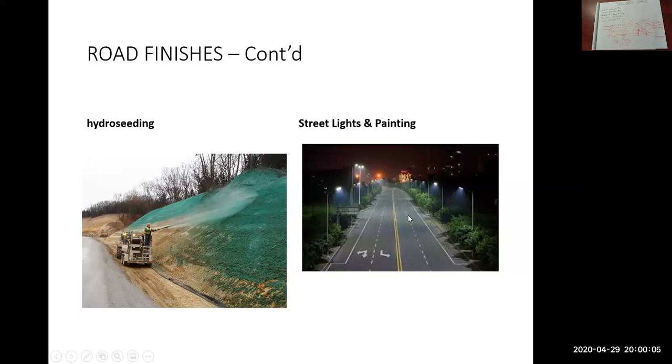The photo on the right here, we have some street lights. There's all the street lights. We've got paint, so you have fog lines or shoulder line here. You've got a dash line, double solid yellows in the middle, another dash, another fog line. You've got arrows that need to be painted. All that stuff will be shown on your drawings, so you can do your takeoff. Trees down the boulevards. Looks like maybe there's a big sign here hanging over the road.